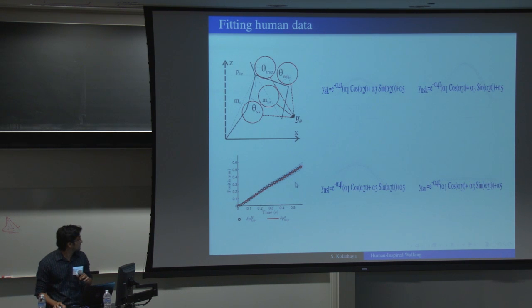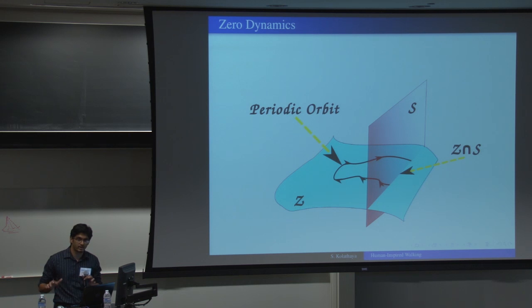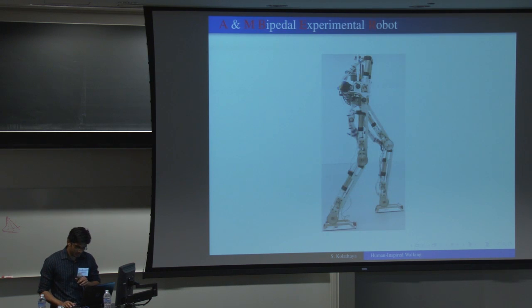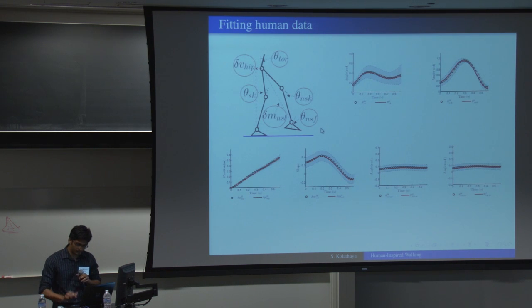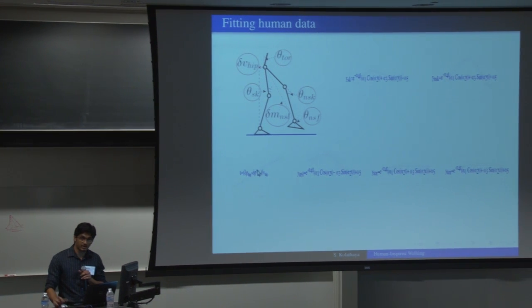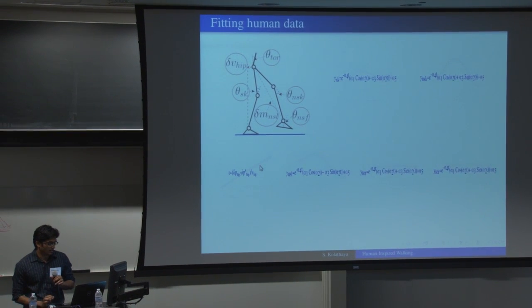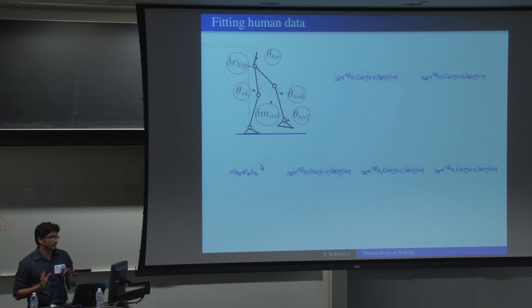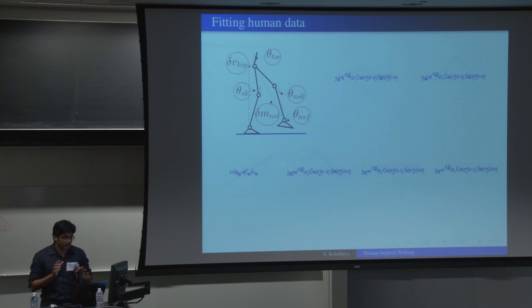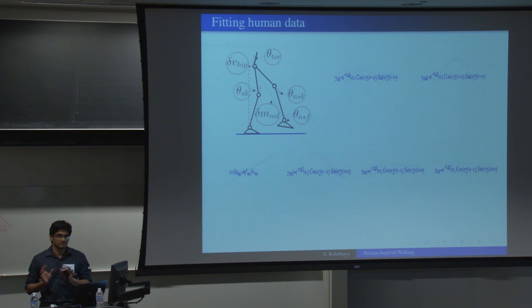So I need to make sure that this output is within a certain region, is stable. So from a control systems perspective, we say the zero dynamics should be within a certain region. Similarly, for Amber 2, it is fully actuated, which means I can track this particular output, but I will relax this output. I say the tracking error need not be 0. It's OK to have a non-zero tracking error for this particular output. And then I say, OK, as long as this is stable, we are good.